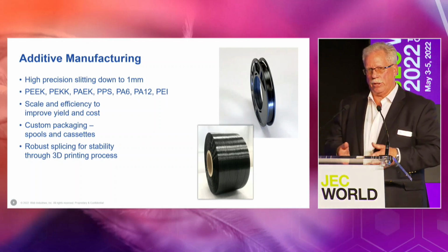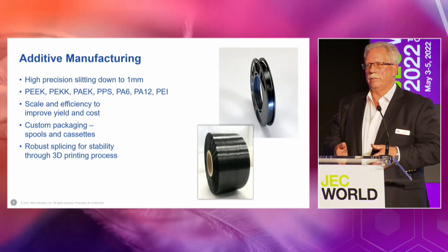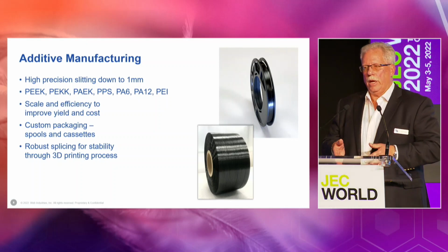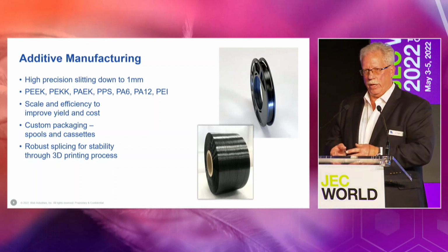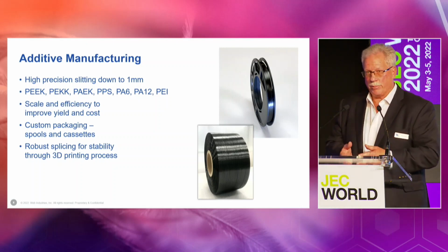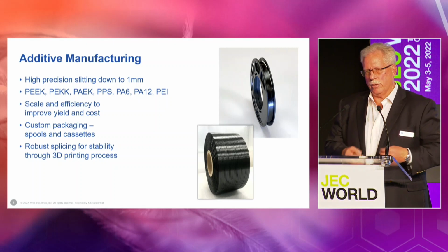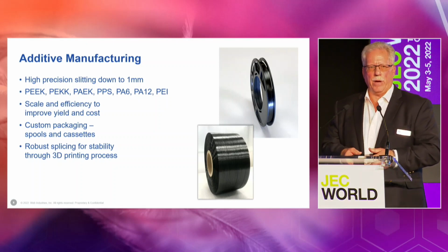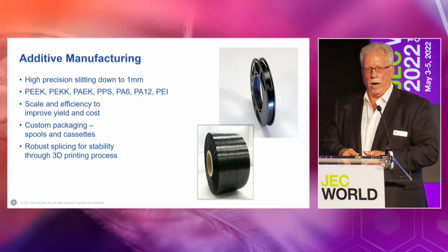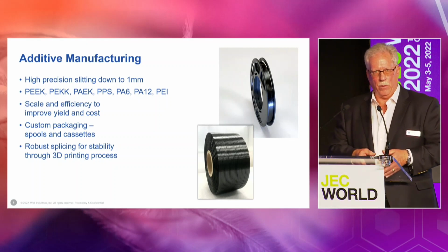The idea is to get the materials in without defects. If they come in with defects and we have to remove them, then we would look at splicing. Some additive manufacturers can accept splicing, which in this case would be thermal, or not. But in order to really make additive manufacturing work right, just like in AFP and ATL, you need to have the flyaway splices.